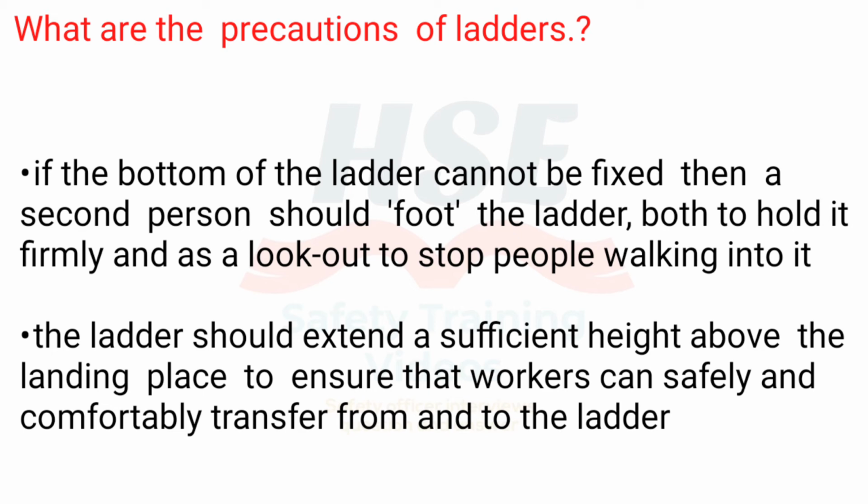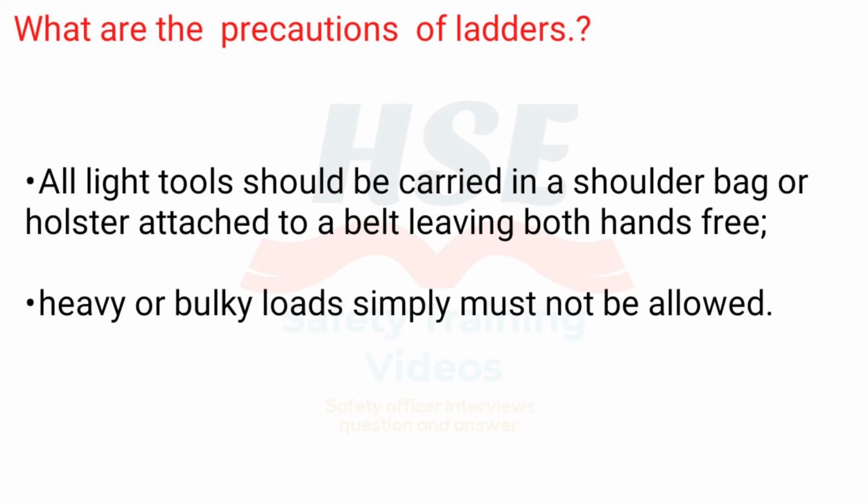The ladder should extend a sufficient height above the landing place to ensure that workers can safely and comfortably transfer from and to the ladder. All light tools should be carried in a shoulder bag or holster attached to a belt, leaving both hands free. Heavy or bulky loads simply must not be allowed.